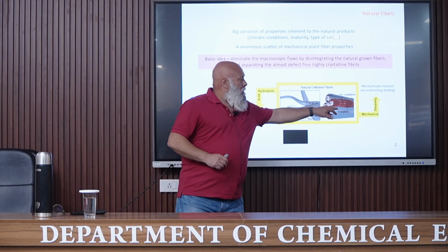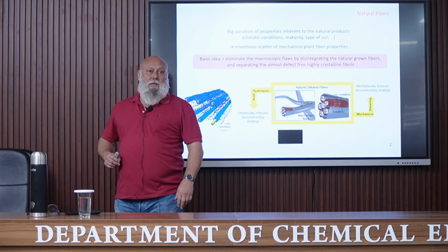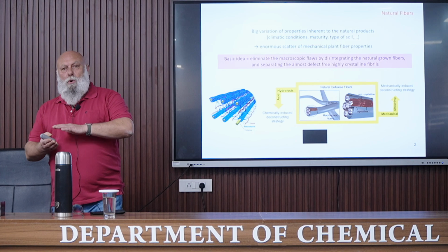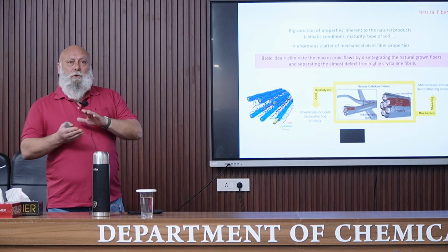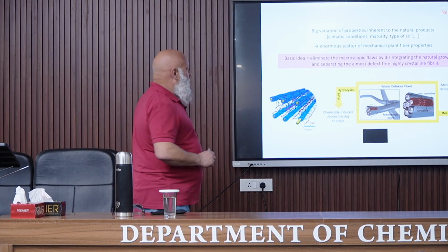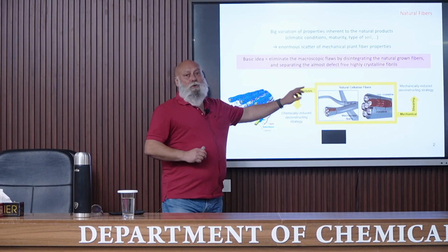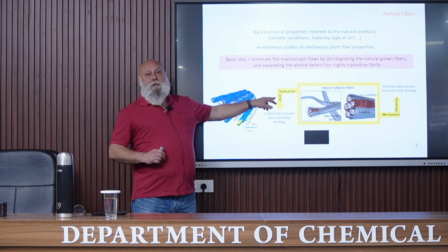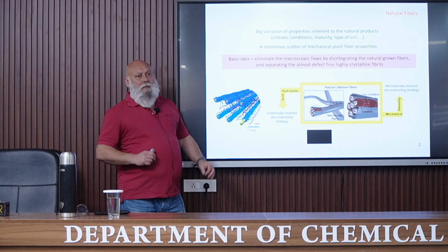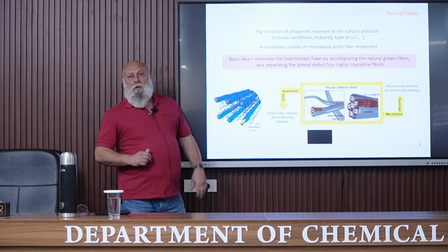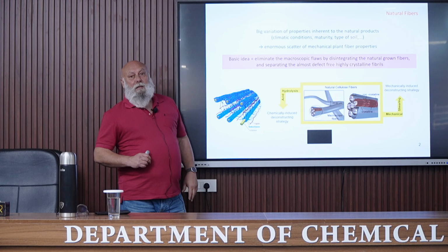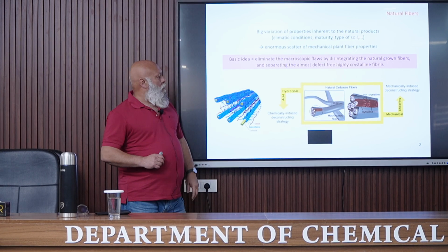The first one is a mechanical treatment. So the objective is to submit this cellulose fiber to a strong shear action in order to progressively release more or less individual nanofibrils. The second option, or the second strategy, is a chemical treatment. In fact, it's an acid hydrolysis treatment that consists in the selective dissolution of amorphous domains. And so we can obtain a different kind of nanoparticles that we will show later.